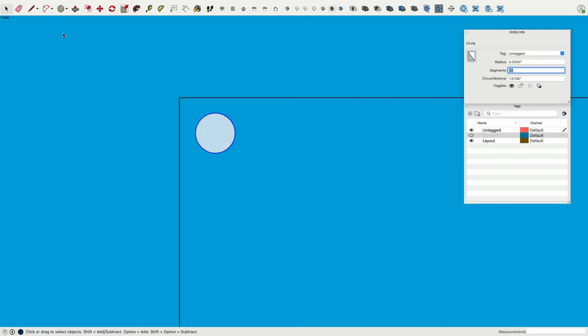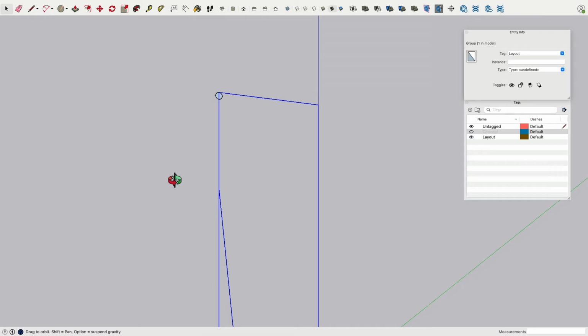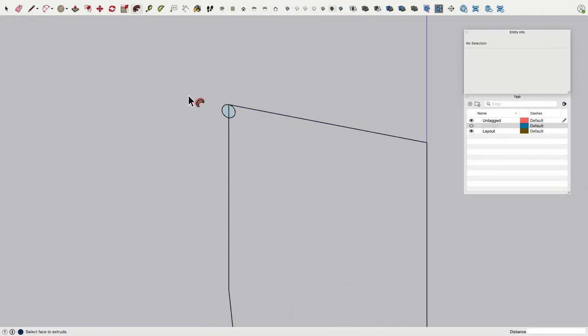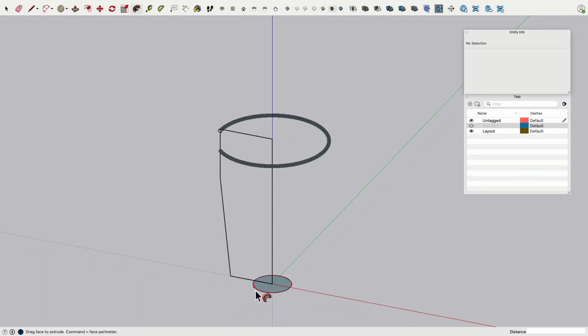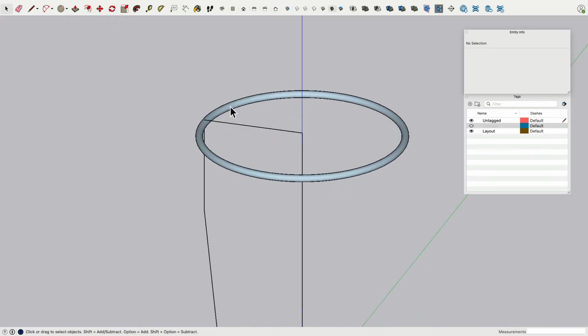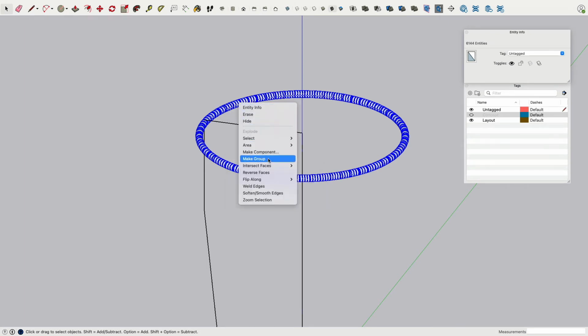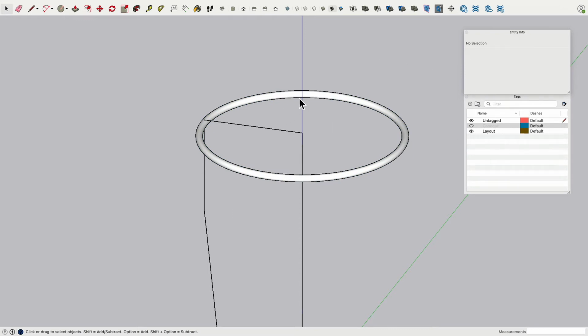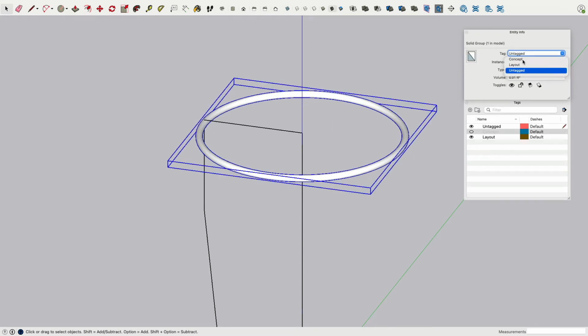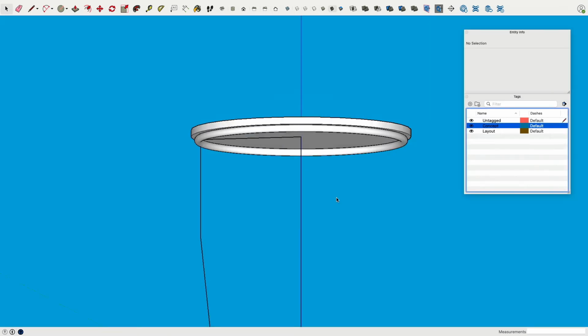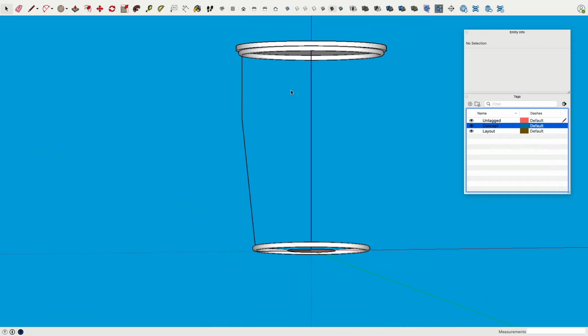Now this point I would like to move to there. Okay, move tool. You see the dashed line is really straight vertical. That's perfect. And then snap to there. So you see this layout thing we created first is just a really nice snapping target. Then same deal. This one along there. Cool. Here, it's blue. So double click and there and there. Okay. And then we move this to concept. And you see, it actually starts looking not too shabby.